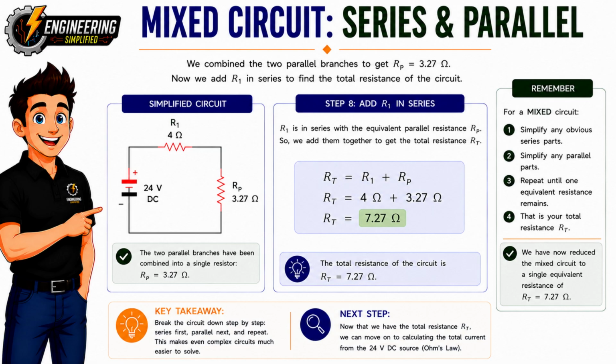That leaves us with a very simple circuit containing just 2 resistors in series. A 4 ohm resistor and our equivalent resistance of 3.27 ohms. Since they're in series, we simply add them together. The total resistance is R sub T equals R1 plus R sub P.